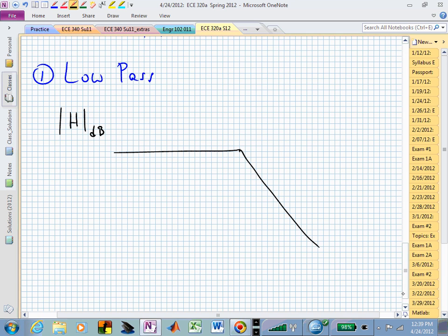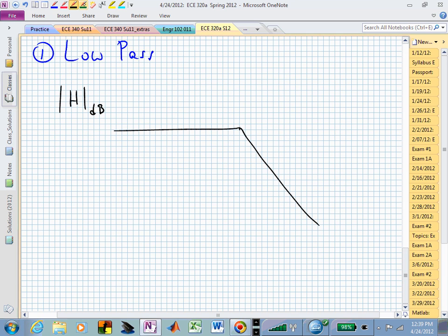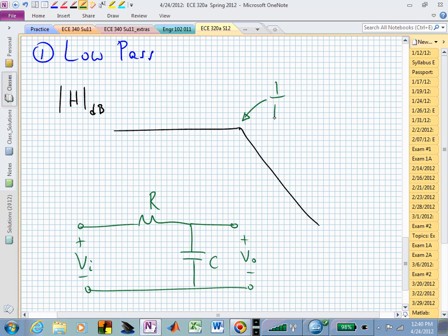One can go here, and another one goes there. And if we were looking at this in terms of a passive circuit, we could now think of this transfer function between the input V sub I and the output VO of this simple RC circuit would provide this kind of a shape, where this point, the break frequency, is 1 over RC.